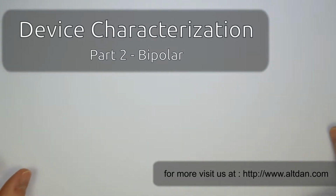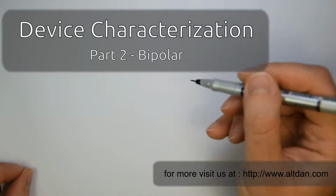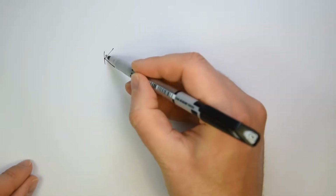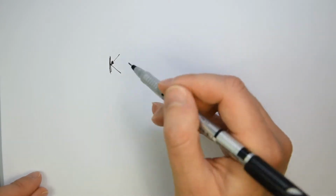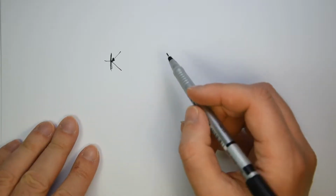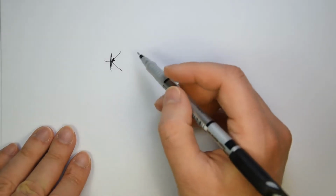For the bipolars, you can do the same thing. And the most important parameter for a bipolar is usually the beta. This is also explained in all the books, and you can usually find this kind of plots. But let's take a PNP, and let's plot the beta versus VB, because it's the easiest way.